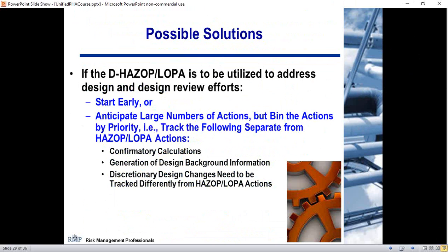Again, if you've got preliminary information, if you design your HAZOP and LOPA to be updated easily, you can go ahead and hit the key scenarios early on and then update it and add more detail as details become available. But the beauty of that is you work out critical things like vessel design pressures, things that are almost impossible to change later. You bring these to the surface early.